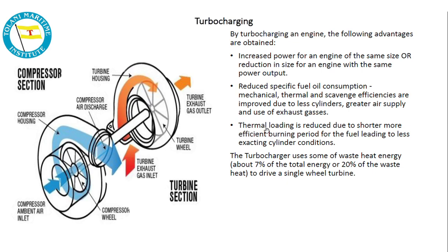Now you see here, thermal loading is reduced due to a shorter, more efficient burning period for the fuel, leading to less exacting cylinder conditions. The turbocharger uses some of the waste heat energy, about 7% of the total energy or 20% of the waste heat, to drive a single wheel turbine. It is a single wheel turbine that is being driven by it.